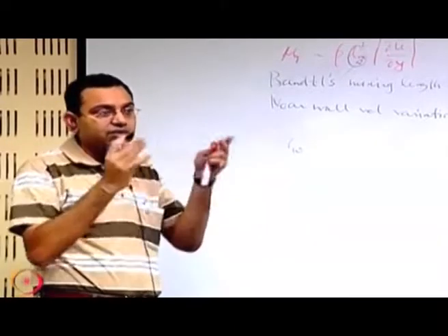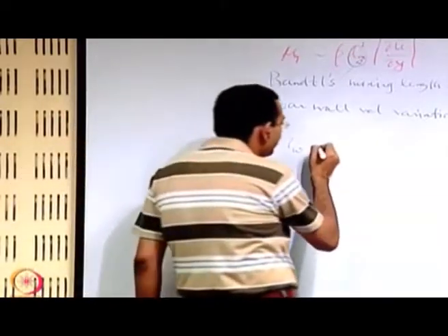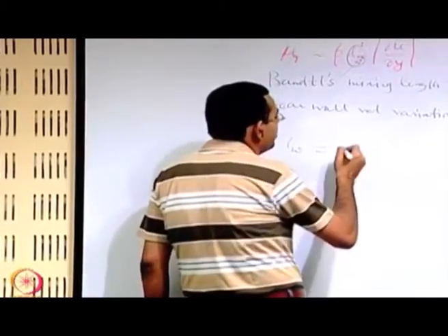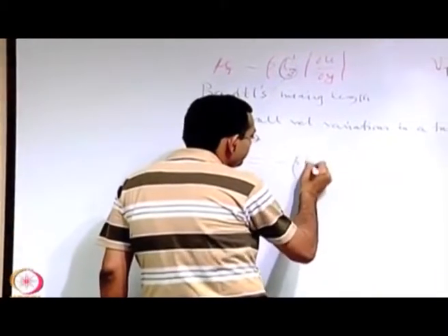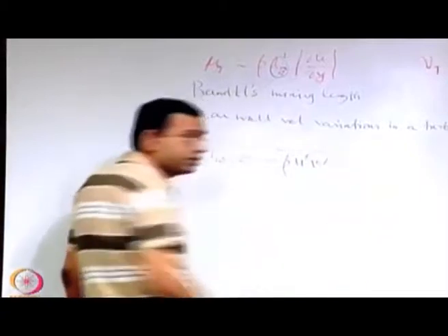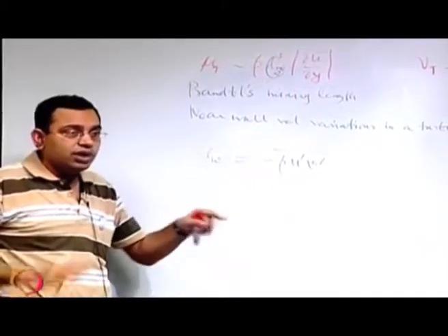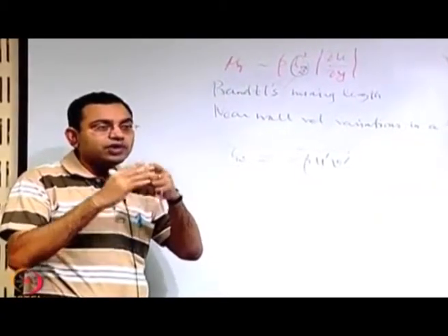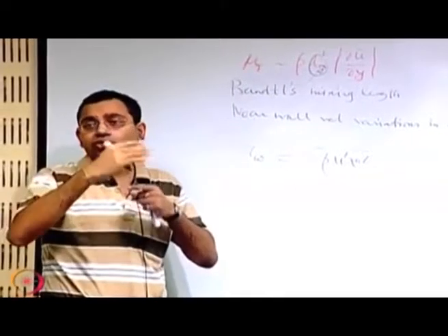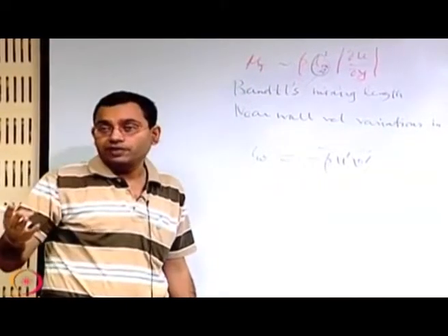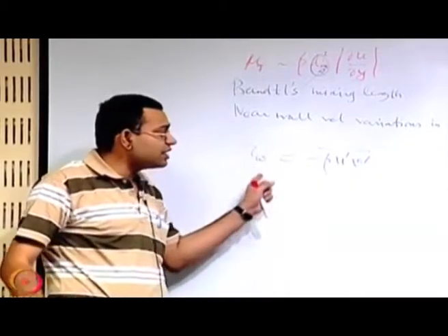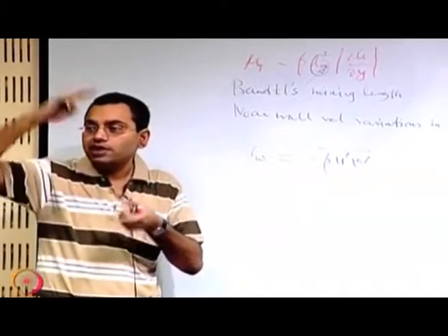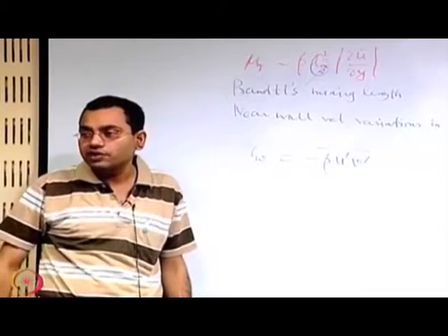So at that overlap or transition, whatever is true is this type of a relationship, this one. So this we are writing for a sort of transition from the wall dominated behavior to the turbulent fluctuation dominated behavior, and it is as if the same momentum flux is being transmitted across those two layers of the transition.